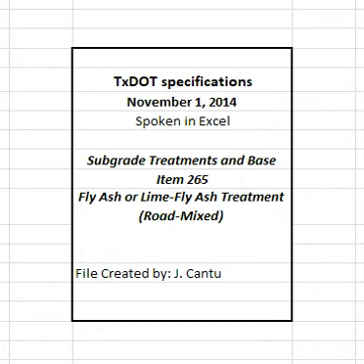4.3.1 Application of lime. Uniformly apply lime using dry or slurry placement as shown on the plans or as directed. Add lime at the percentage determined in section 265.2.7, Mix Design. Apply lime only on an area where mixing can be completed during the same working day.